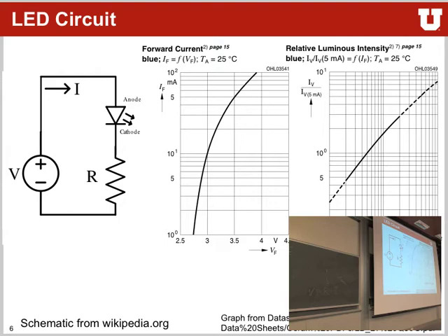Many microcontrollers these days can do both about the same. Others actually have special high power pins that can source more current than they can sink. So sometimes you really have to go into the schematics and read up on how much current you can sink or source. With the small little LEDs we're using, 10 milliamps, sinking is usually no problem. Yeah, good? All right.